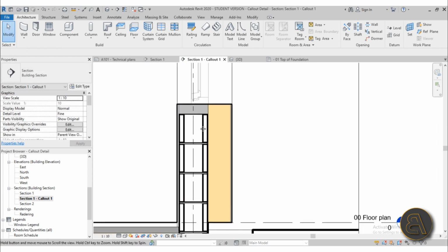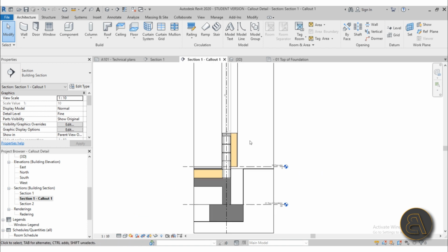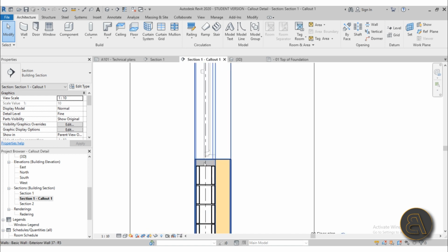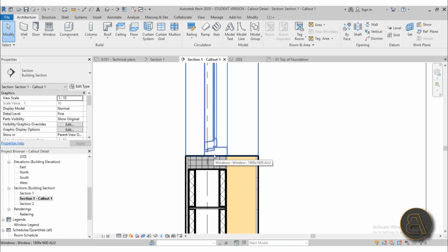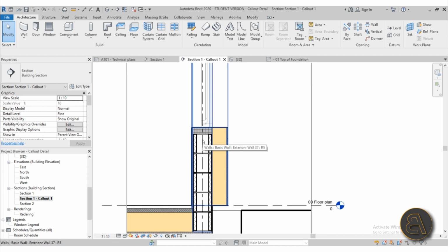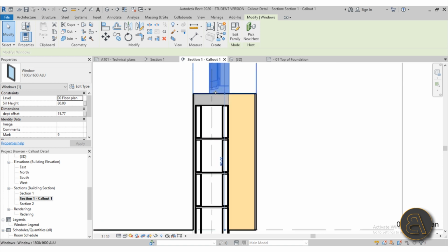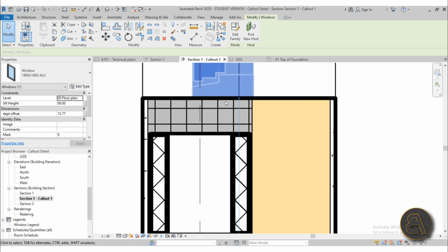Now this really explains how Revit is meant to work. You can create a callout, and then here you can see if there are some potential problems with your design when you get to construction details. So in this case, I would like to fit 5 of these CMU blocks, and then have a small gap between the wall and the window.